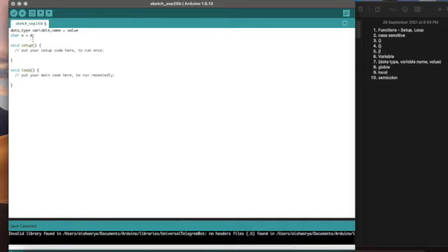So here you are declaring a value d. This is our value, this is our data type, and this is our variable name. In case you are writing it for a number, it can be an integer. So here we are going to use int, and we will name any integer. I'll just name it as number and the value to be 3, and we need to put a semicolon. Always when you write Arduino programming, it is necessary to put a semicolon for every line. So this is how it works.